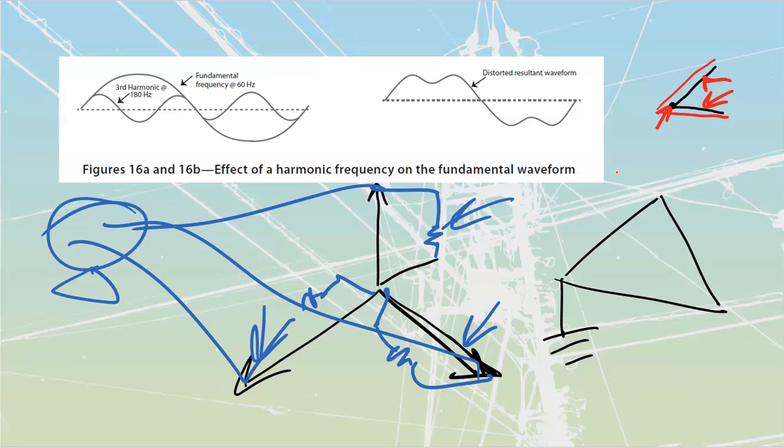It also leads to a lot of vibration and mechanical issues, because we're going to get big magnetic field, tiny magnetic field, and then big magnetic field, and then tiny magnetic field again. We don't like to see those types of operations because it causes mechanical problems like bearing wear or imbalancing of our stators and stuff like that.